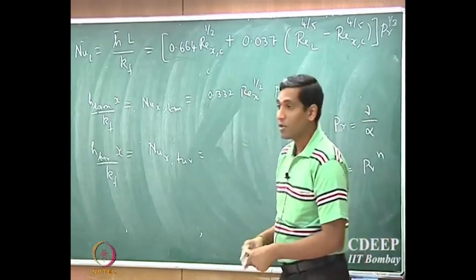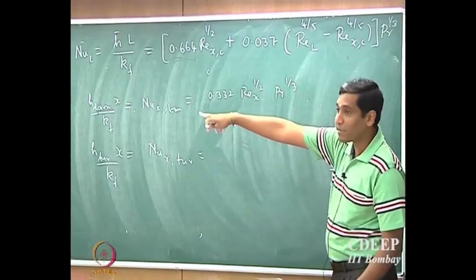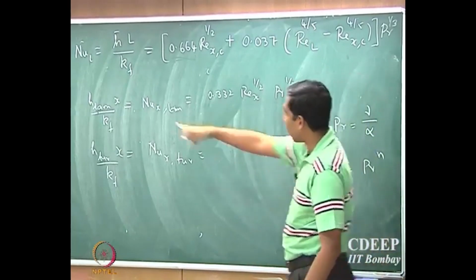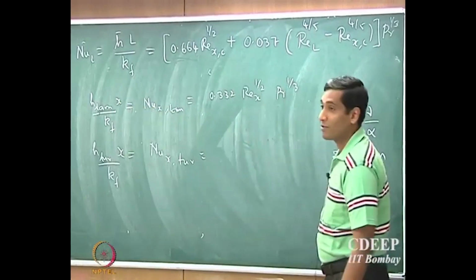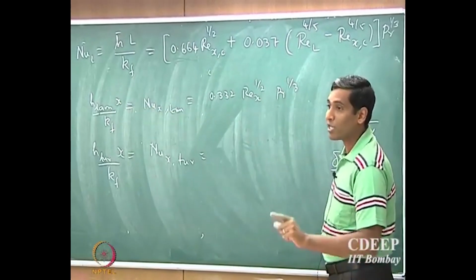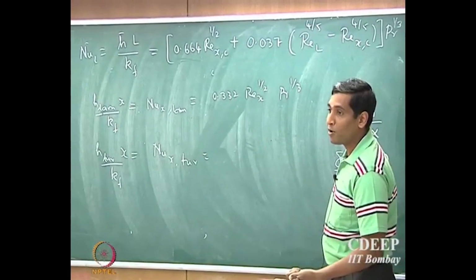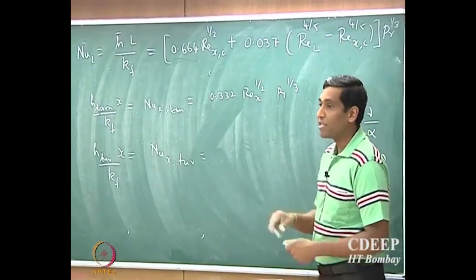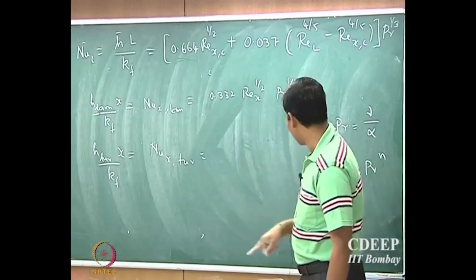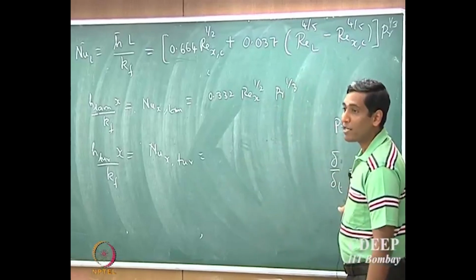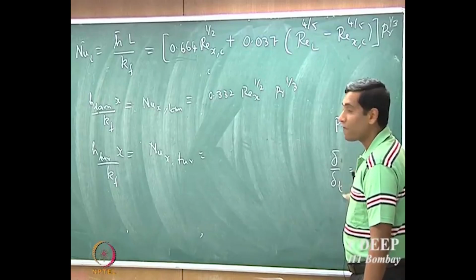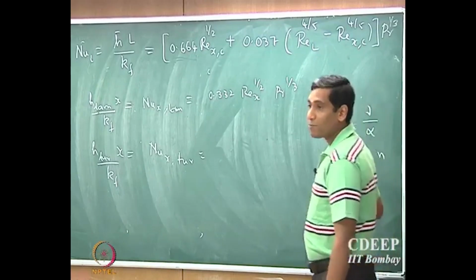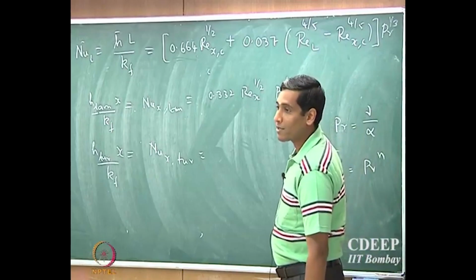Yeah, that's true. So it turns out for flat plate case it's the same. So note that it's not just the hydrodynamic boundary layer which changes. This is the ratio. Be careful, it's a ratio. It's both the hydrodynamic and the thermal boundary layer actually is changing. Now when it comes to Prandtl number less than 0.6, the variations that you get in turbulent flow is very different. So you have to be careful how it is defined. This problem comes only when Prandtl number is less than 0.6.